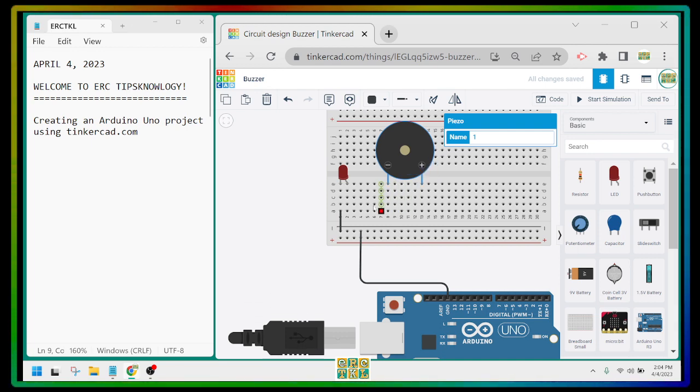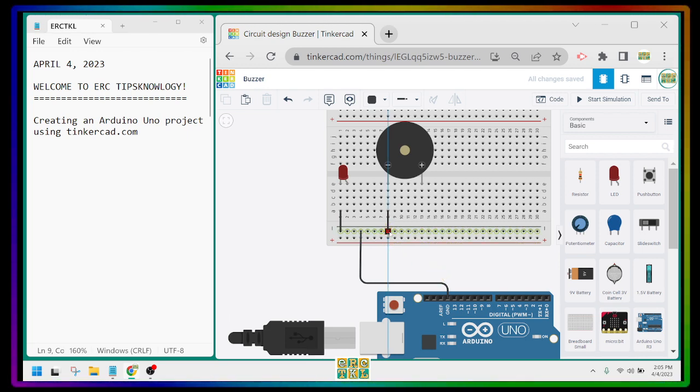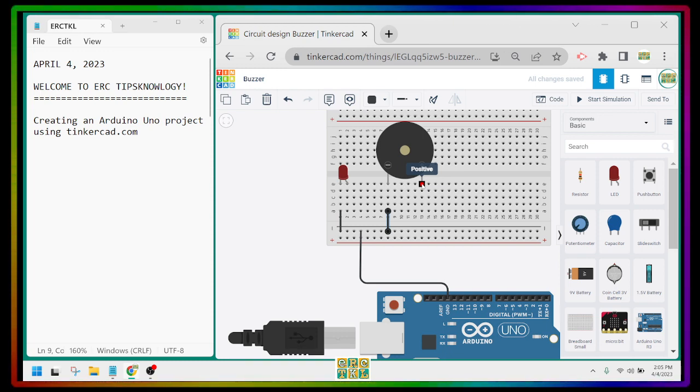E13. So letter E number 8 is also connected to A8, B8, C8, and D8. So you can take one hole here, A8, and connect it to your digital pin for the ground. I may put it here, but because we are using the breadboard, I'll just connect it to the negative of the breadboard, on the row for the negative. And for E number 13, which is the positive of the buzzer, we can just connect the letters A, B, C, D to the digital pin number 8.